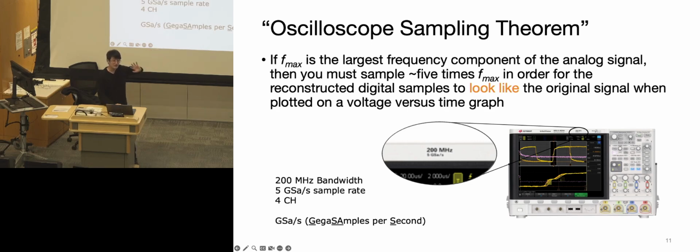So this just gives you some intuition for when you're trying to choose your ADC sampling rate or ADC chips, if you want to go even faster than what we can provide on STM. These are the factors you should be considering. 2 is great, but in real life, do 5 or higher. Any questions regarding the sampling rate?